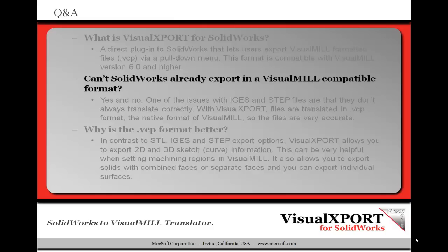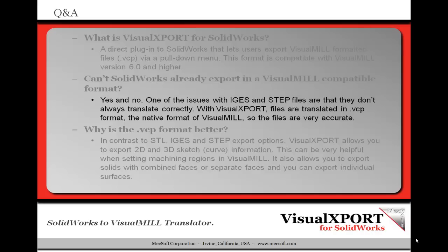Next question. Can't SolidWorks already export in a VisualMill compatible format? The answer to this is yes and no. One of the issues with IGES and STEP files, which are formats you can export from SolidWorks to VisualMill, is that they don't always translate correctly. With VisualXPORT, files are translated in .vcp format, the native format of VisualMill, so the files are actually quite accurate.